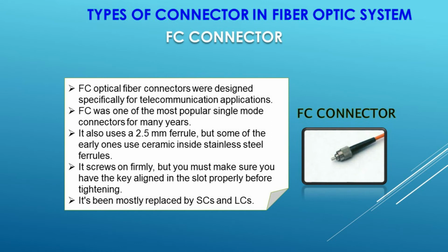FC connector. FC optical fiber connectors were designed specifically for telecommunication applications. FC was one of the most popular single-mode connectors for many years. It also uses a 2.5mm ferrule, but some of the early ones use ceramic inside stainless steel ferrules. It screws on firmly, but you must make sure you have the key lined in the slot properly before tightening. It's been mostly replaced by SCs and LCs.